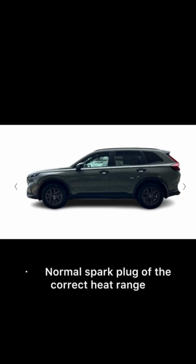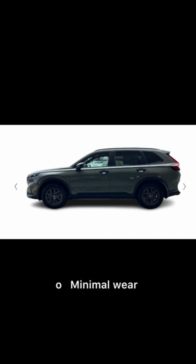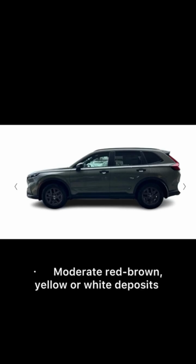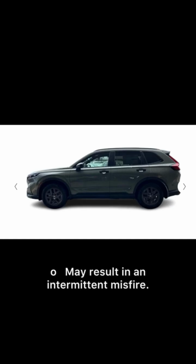Normal spark plug of the correct heat range: light traces of deposits that are light gray to tan, minimal wear, no cracks or carbon tracks in the insulator. Moderate red, brown, yellow or white deposits from fuel additives and mild oil consumption may result in an intermittent misfire. Glazed deposits on the insulator core nose indicate melting of certain deposits on the insulator. Deposits can become conductive, shorting out the spark plug.